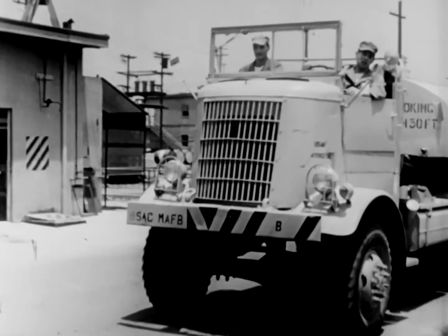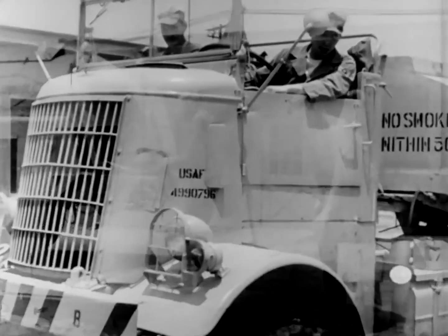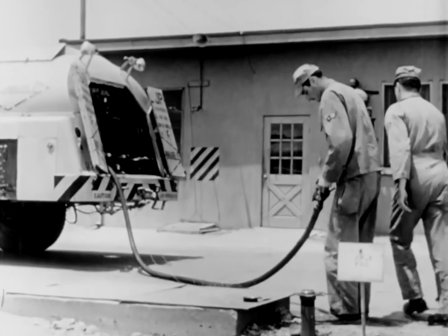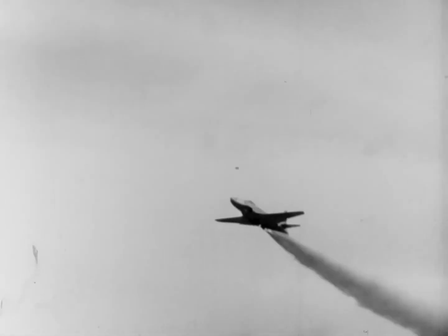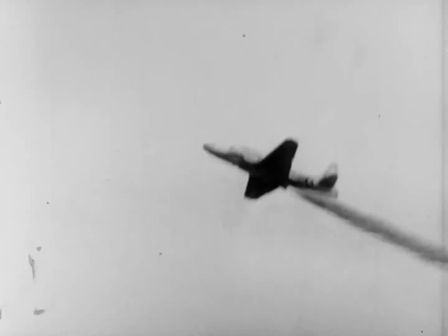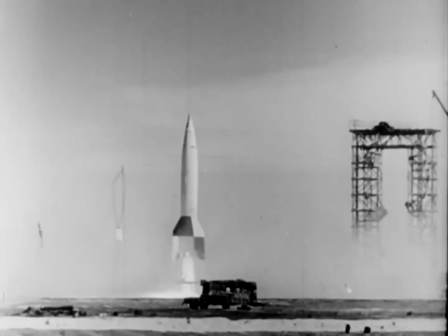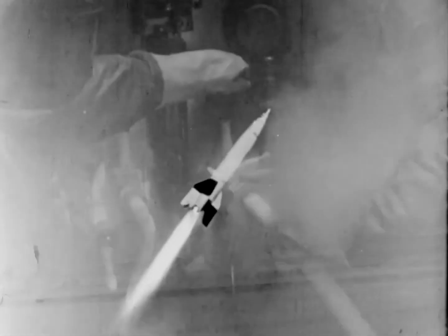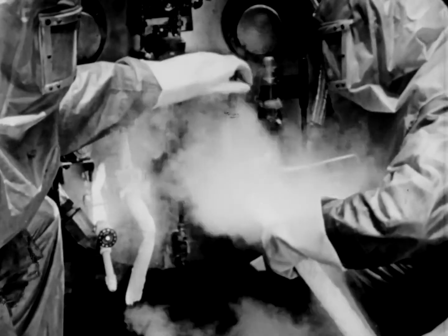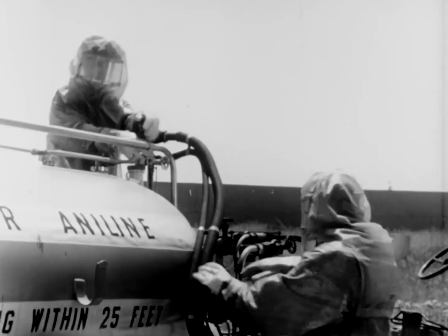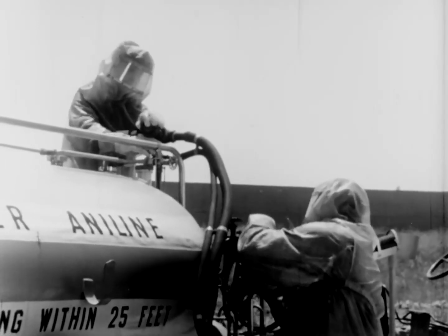Alcohol and petroleum are ideal fuels because they are readily available, non-poisonous, they store well, and are comparatively easy to handle. It must always be kept in mind that rocket propellants are capable of unleashing more raw energy than any other known fuels. The devastation which could result from the least carelessness or lack of familiarity with precautionary measures makes it mandatory that no person handle propellants until he's been thoroughly schooled in proper methods and safety procedures.